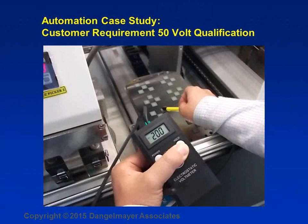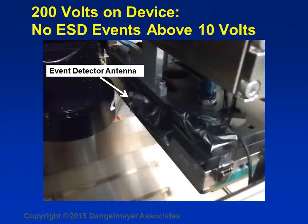But it turns out that even though the device was charged to 200 volts, damage was not occurring, and we determined that with the use of the event detector. Here we placed the event detector strategically immediately adjacent to where the product was being processed at that 200 volt reading.